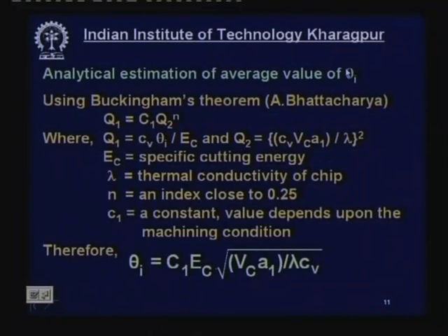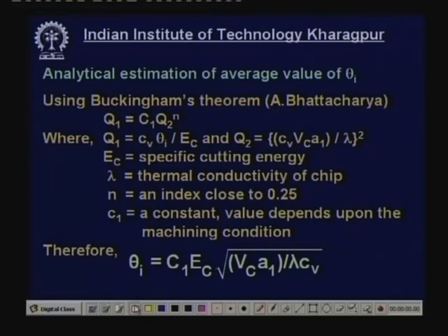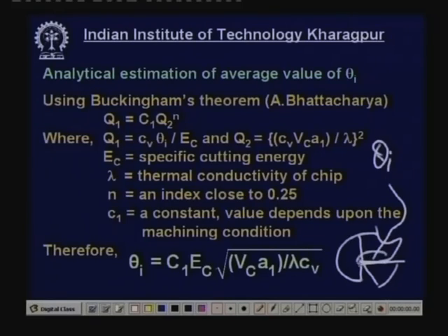Now, this is another analytical estimation of the average value of the chip tool interface temperature. I remind you that this is the tool and this is the rake surface where the temperature is theta I. This has to be determined, the average value of theta I. How? There are many methods, very beautiful methods available in different books, including A. Bhattacharya's book, Machining Theory and Principle.